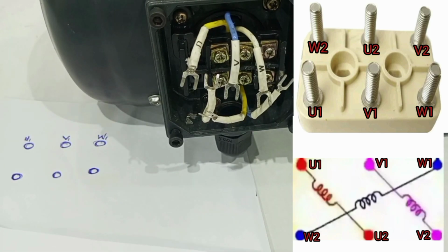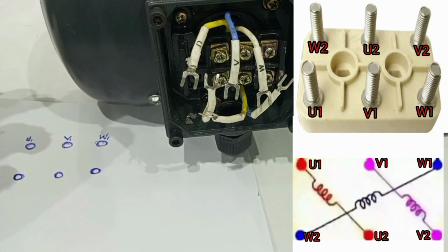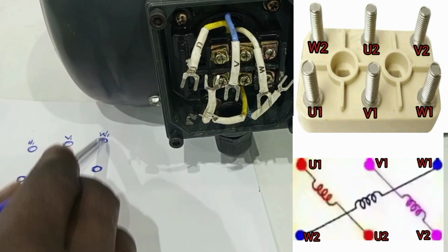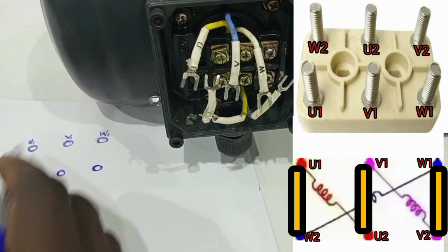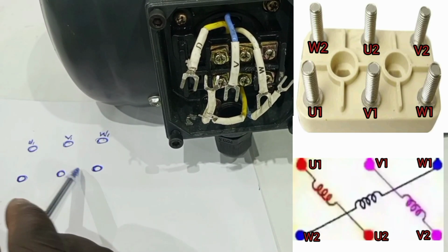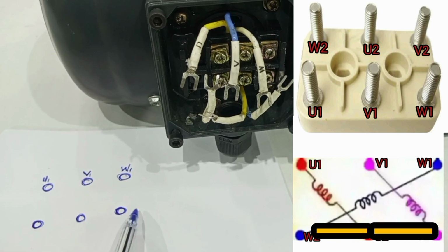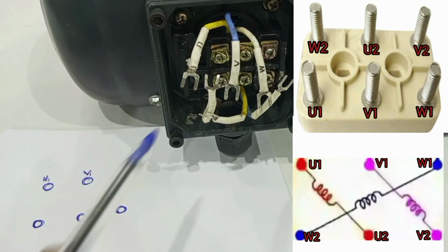All right. So here, we want to arrange these terminals in a way that by just using the same set of strips, we should be able to connect the motor in delta configuration by vertically connecting the links between each two terminals. And then when we want it in star, we can use the same links to just bridge one side of the 3 terminals. Okay, and that is why the terminals are arranged like this at the motor terminal.